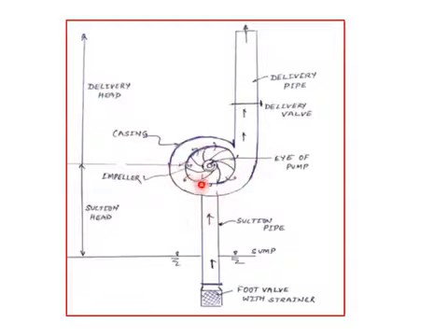So now, as I told you previously, when the water is made to rotate by an external source, the impeller will do work on the water. So here the water will be thrown away to the outer circumference, hence a centrifugal head will be impressed here, and because of this centrifugal head that is impressed, water can rise to the higher level.